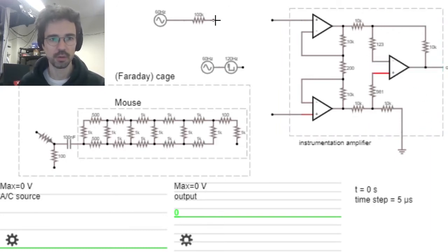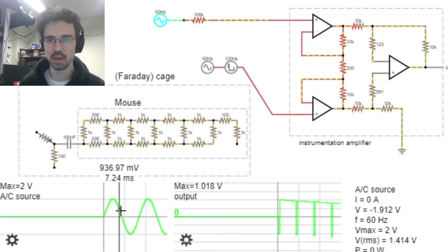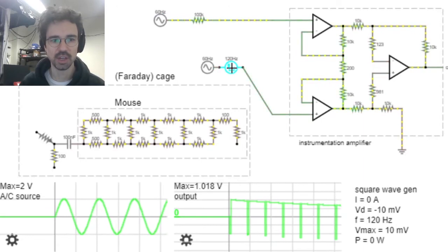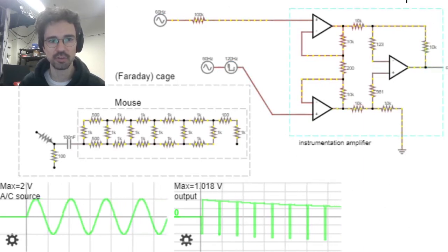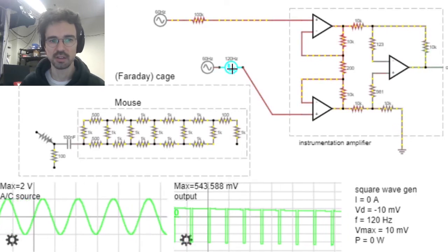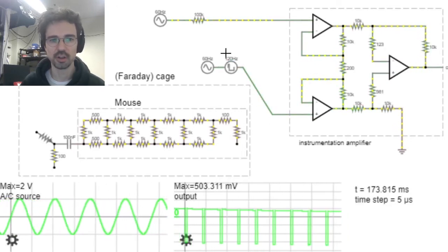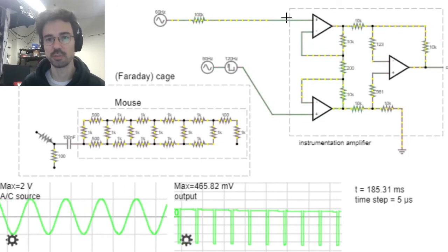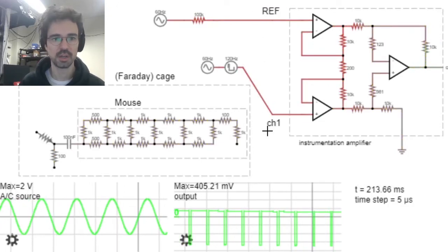And previously we had considered a situation like this. On the left side, you have a common mode noise, and then we add to that our spike signal here, and we're using the instrumentation amplifier to separate out the spikes that, despite being small, are only present on one of the inputs and not on the reference input. So this would be the reference input up here. This would be our channels, and then wherever we have a ground symbol would be our ground.